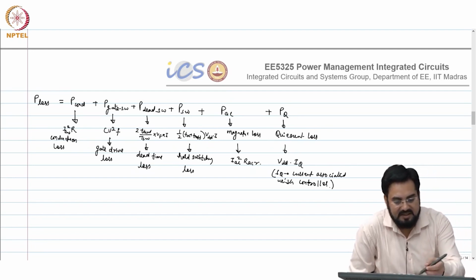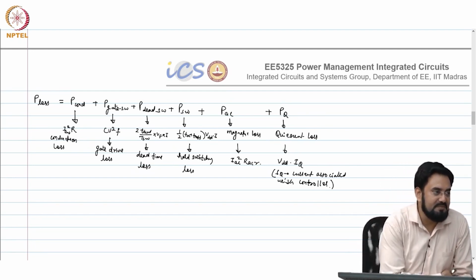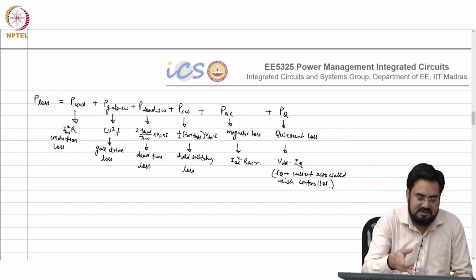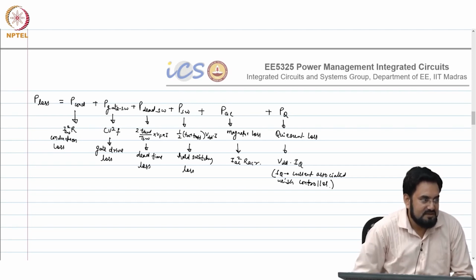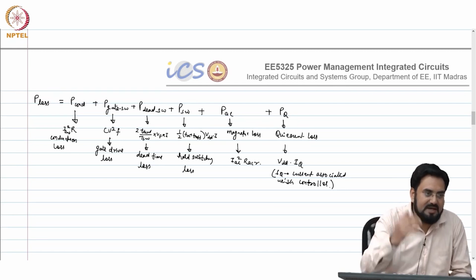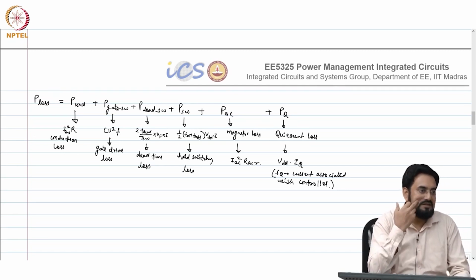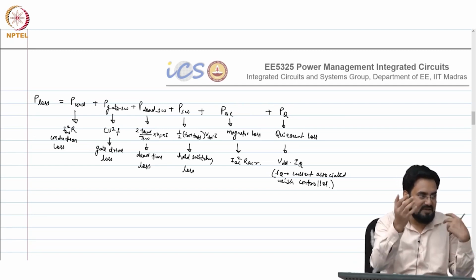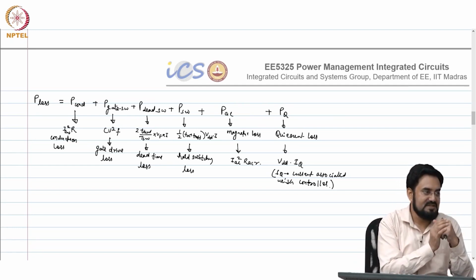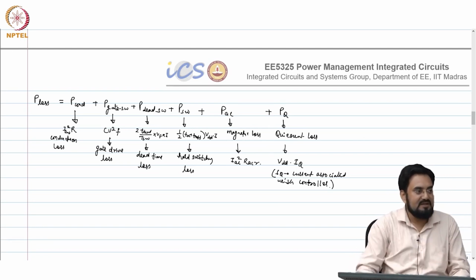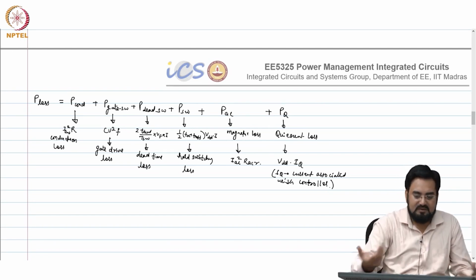Your magnetic losses, usually if you operate in PFM, since it is a function of AC, you are operating at a lower switching frequency, so your magnetic losses will not be that dominant. At light load, we already talked about one way you improve the efficiency, by reducing the frequency. But this IQ will be fixed.